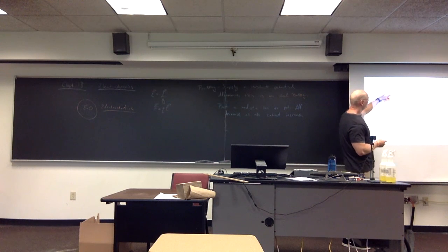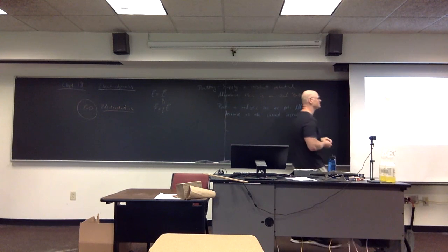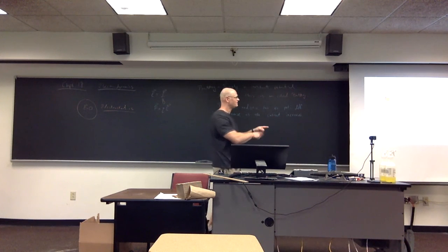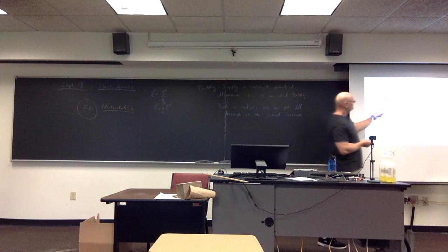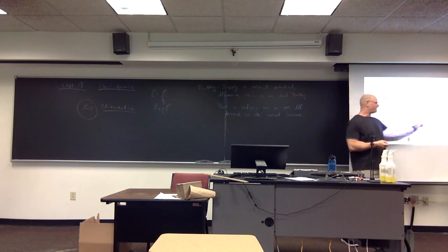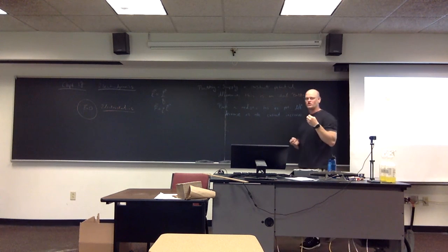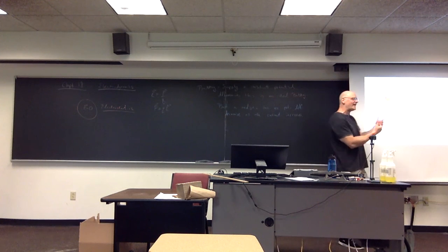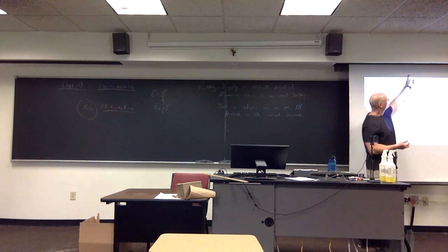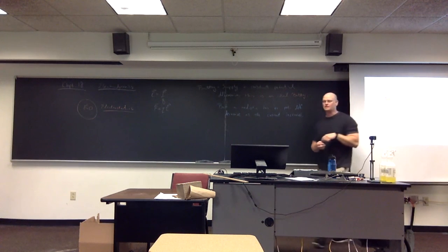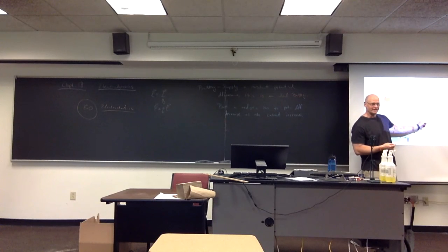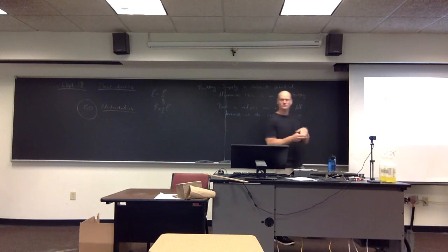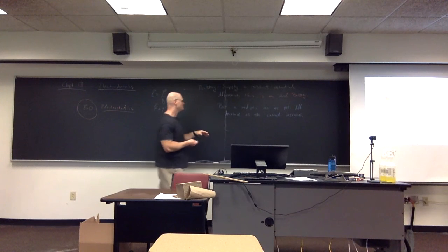Now, what happens when I apply a current to the system, so I put wires onto it and have it go through and run, say, a radio or a flashlight? The rate at which this is being dissolved and the rate at which these negative charges are going into the electrolytic fluid stay the same, but now I'm causing electrons to move through my system, and that happens at a much faster rate than what these are being depleted, which causes the potential difference across the battery to decrease. So this is why I have a realistic battery where the potential difference decreases.